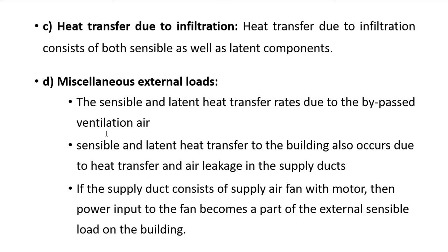So other than solar radiations and infiltration load, there are some other miscellaneous external loads. It includes the load due to ventilation air. So we have to provide fresh air supply to the room. For that, we are always supplying some fresh air from the atmosphere.